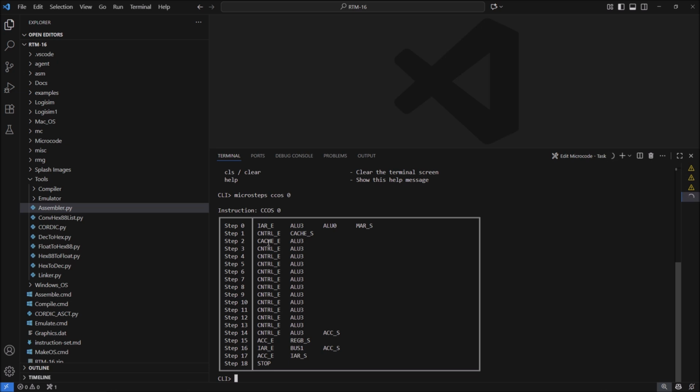and then we enable that cache onto the bus. Now the only difference here really is that instead of choosing the number 7, which was the number for the sine function within the CORDIC unit, we're going to use the number 8. So ALU 3, so that's 1, 2, 4, 8. So this is number 8. And this generates the cosine function. Now we could in fact have just used the number 7 and it would still generate the cosine function, because whether we use 7 or 8, we're going to generate the sine function and the cosine function.